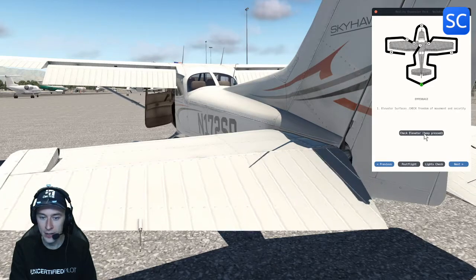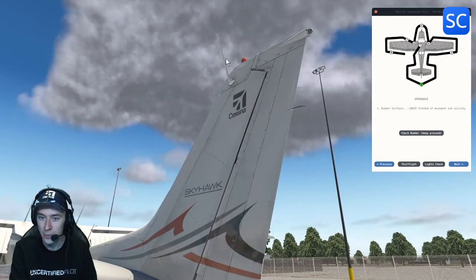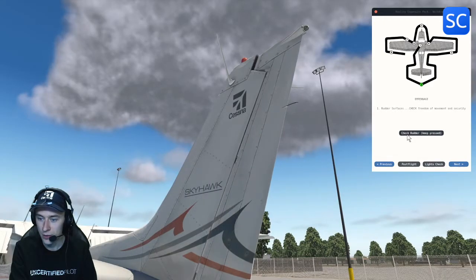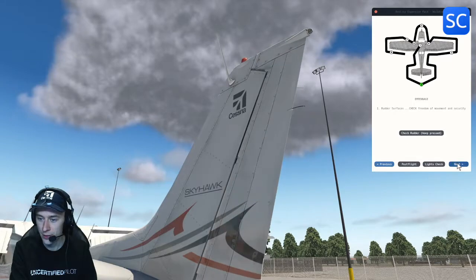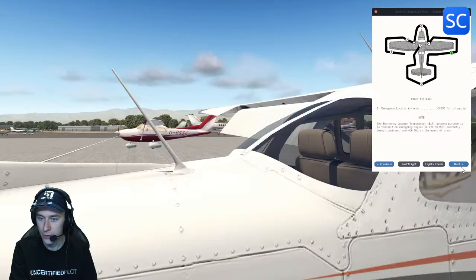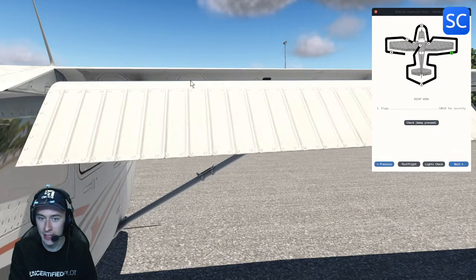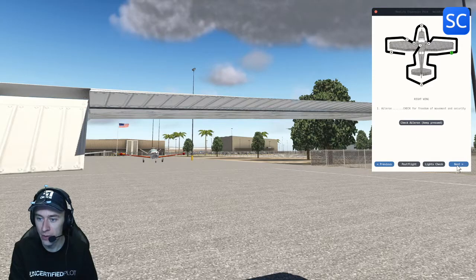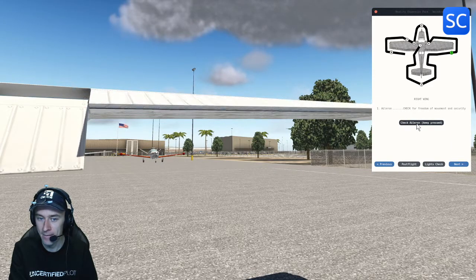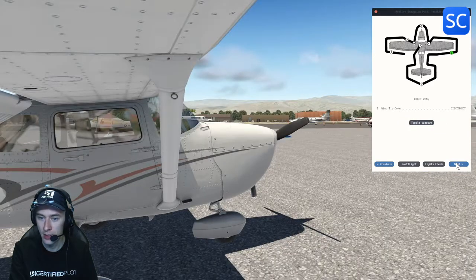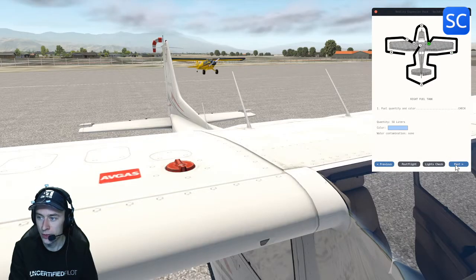Checking our elevators, and we should also check all of the connecting rods and all of the other stuff, inner parts here. Go up, nav antennas, everything looks good. Rudders, tie-down is removed, ALT antenna looks secure. The flaps have a wiggle, that's good. And again, we should check all of these inner components here as well. Ailerons look good. Tie-down is removed.